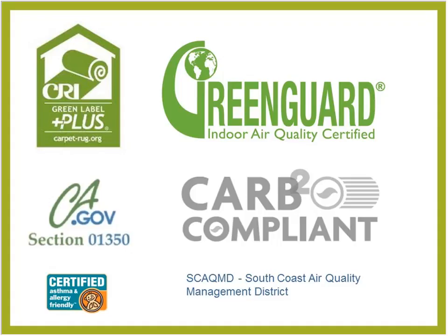Basically, when you install cabinets with exposed edges, there's a chance that's adding formaldehyde to the house. So one strategy is to seal that, ideally with a California-certified sealant, or you can get the cabinets as CARB compliant and make sure they don't have formaldehyde in them. So that's another thing to check out. And then underneath that is the South Coast Air Quality Management District. That's another certification for materials, making sure they meet low VOC content.